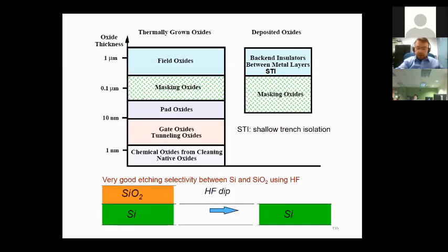Okay, so based on the type of different oxides, they can be listed with respect to their thicknesses too. The field oxides were mainly for insulation, right? So their thickness is at an "I don't care" level. They are too thick. As we go to the more precious items like the gate oxide, one of the main building portions of the transistor, their thicknesses are of course much thinner, and the quality has to be super good.